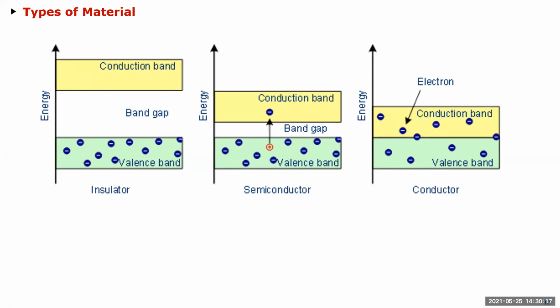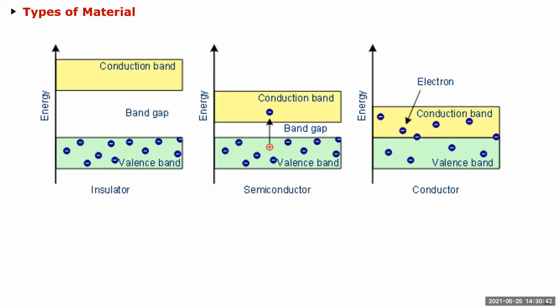So as you are applying higher and higher voltage, a higher electric field is created because more charges are on the plate. But at a certain point, I was showing you that the dipoles are stretched, right? And it kind of looks like a little tadpole with positive and negative ends at both ends. But there is a certain electric field for every material where that will rupture and break down.